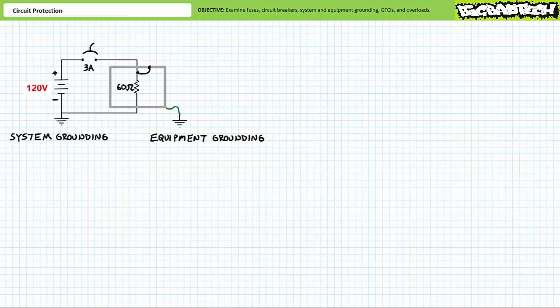In addition to saving operators from inadvertent shock hazards, the equipment grounding conductor, by electrically connecting the frame to the reference plane upon which operators stand, also limits something known as a touch voltage to that same ground potential. This allows any accumulated static charge on a device to bleed off to ground. In summary, bonding the frame to ground purposely creates a low resistance path to ground, so overcurrent protection devices like fuses and circuit breakers can operate as intended, and operators always touch things at the same potential as that which they are quite literally standing on.